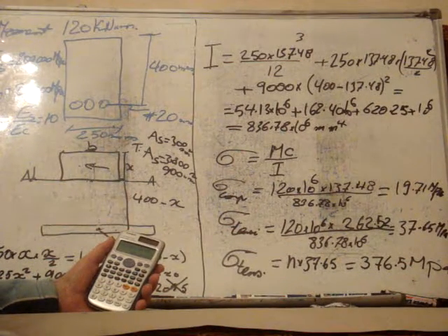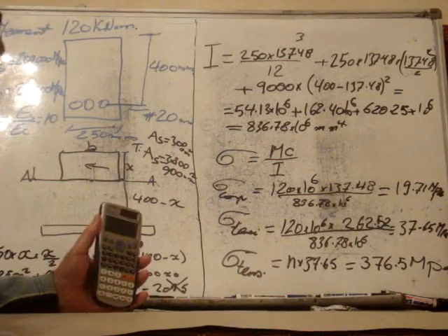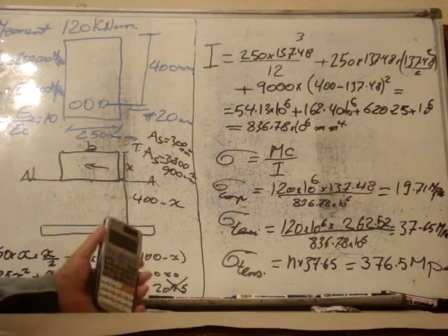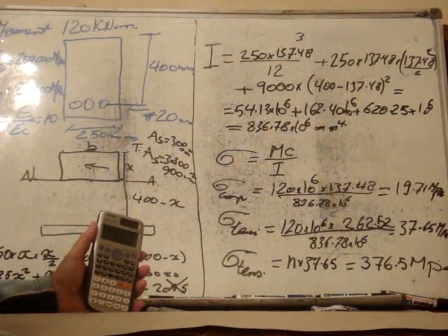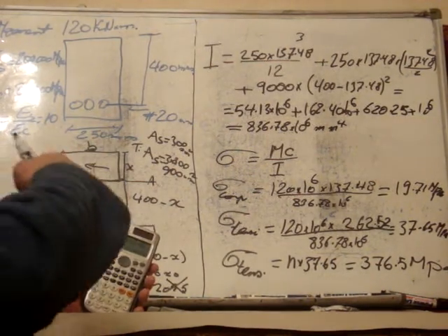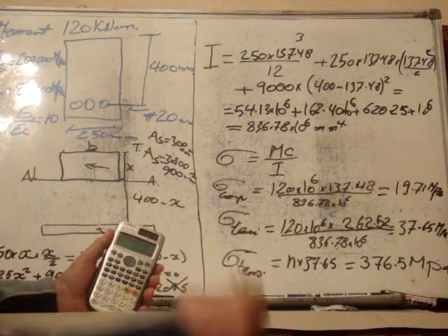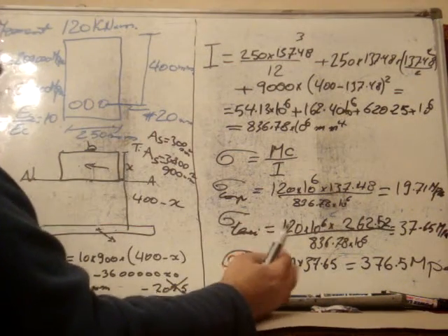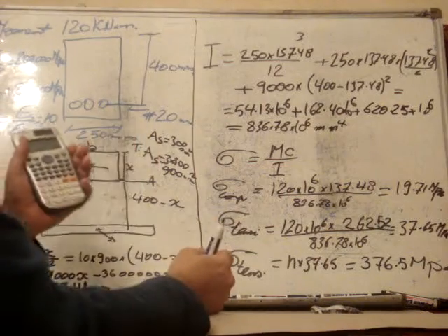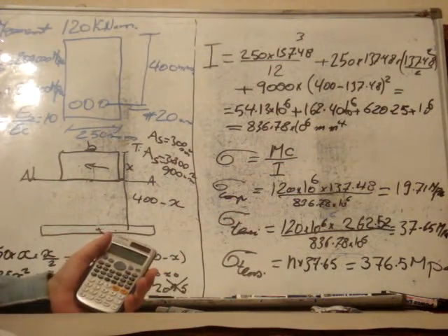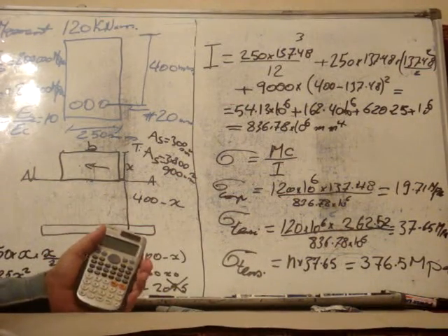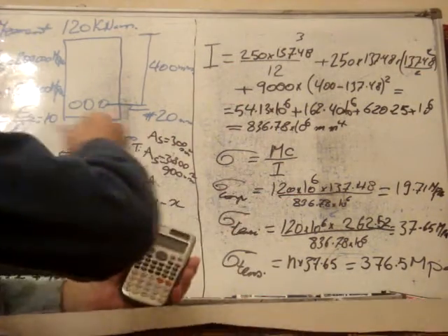Now, to do exactly the same calculation if we have a slab, the problem is that slabs have a wider distance for b, and we can assume this b equal to, we take part of this slab, 1 meter, and we use it exactly the same way.